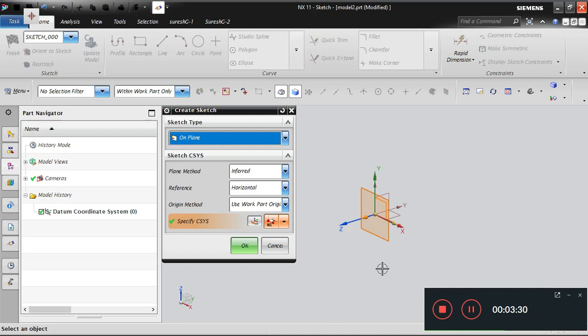The drawing shows a front view, so you have to create the same front view. When you go for the right side view, whatever view comes should represent what you have in the industrial input drawing as well. It should not differ from each other. That is why sketch orientation is very important. If the sketch orientation is wrong, the model has to be redone newly, no other option.